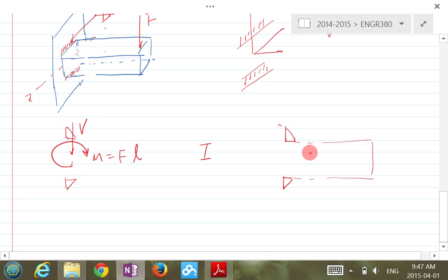Now I'll pick a location, a critical location that gives us the most critical stress. It's a pretty small weld, and it's hard to tell which is critical, like in the previous case. So you can actually pick any point within the welds here, because the length here will be negligible compared to the length of the bar, for example.